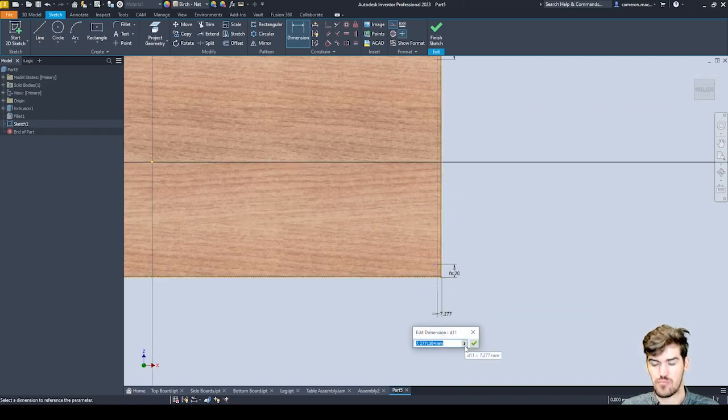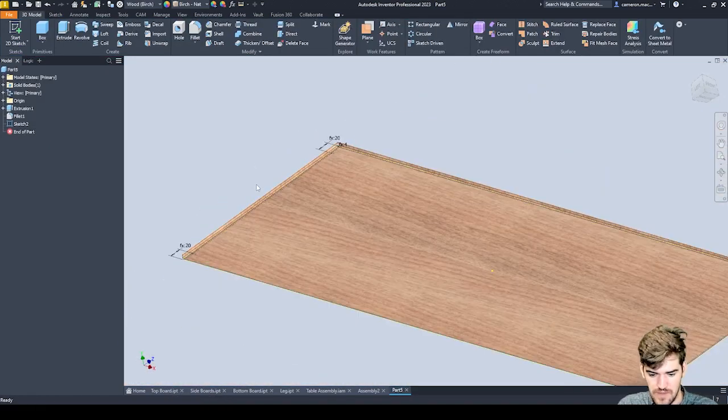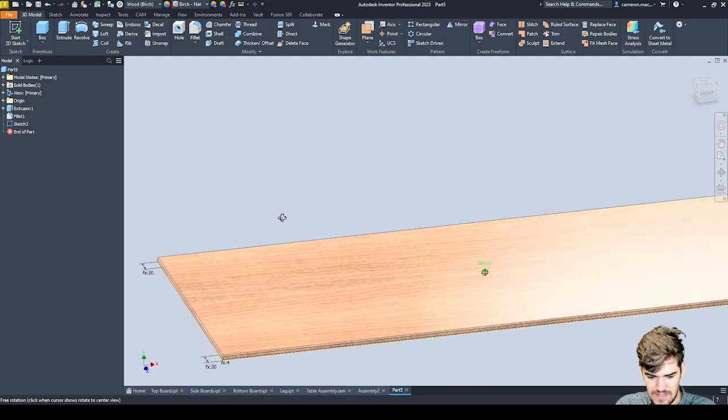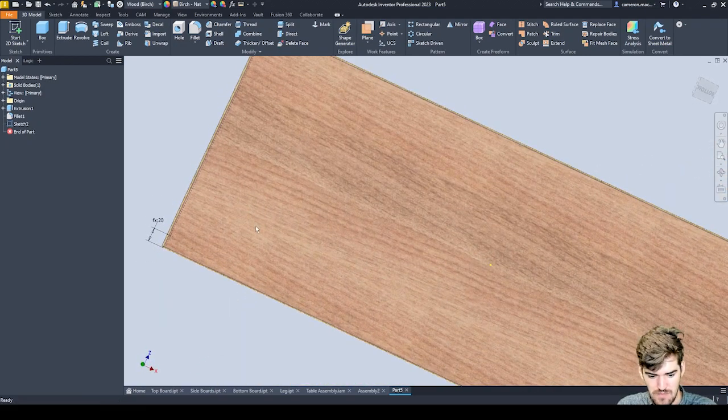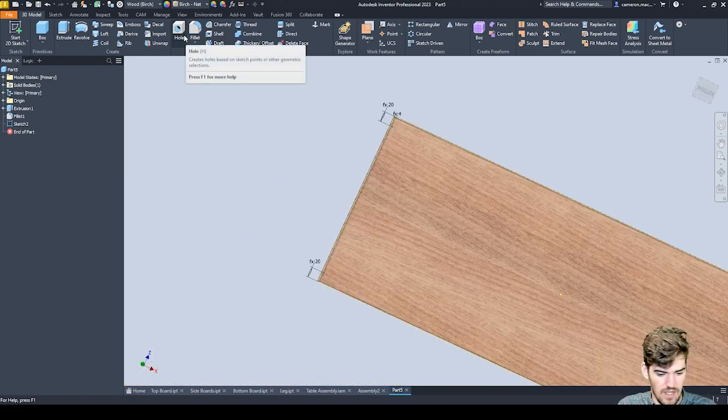And if I go and press a little triangle on the side there, I can pick from various other parameters as well. Otherwise, I could type this value in if I know that it is whole offset D, or W in this case. Hit enter, and it grabs that same value. So there are multiple ways of grabbing other values as well as we go through. As soon as I hit finish sketch on here, that's then created for me. All I now need to do, make sure I've got the alignment correct. That's perfect. We're on the bottom of our part. I want to now add in holes for this particular part.